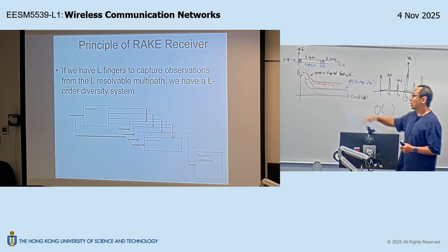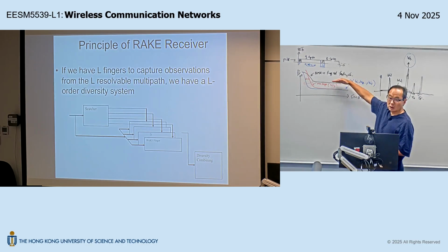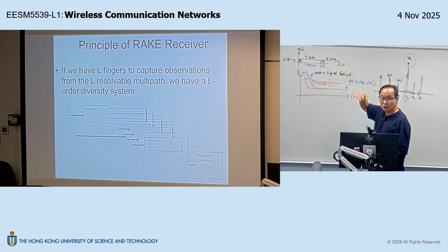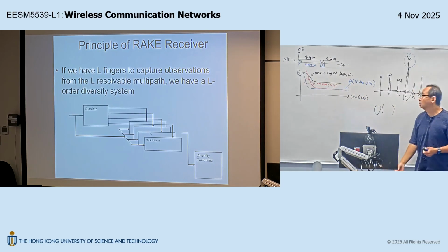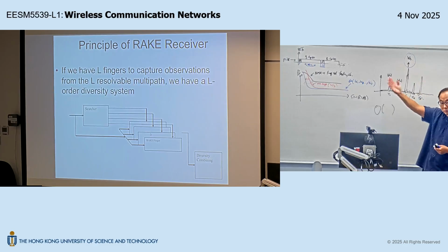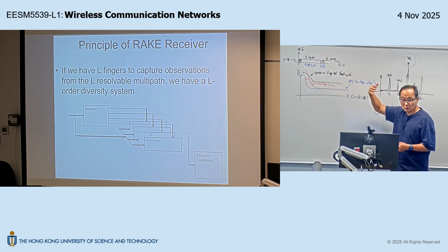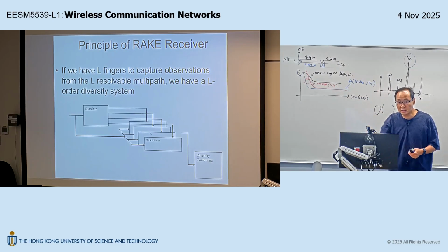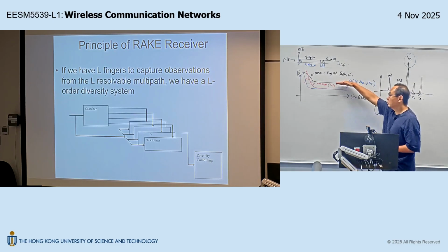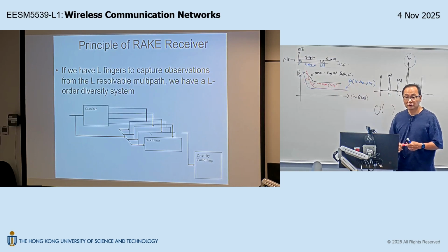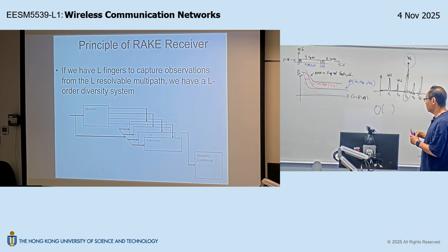Is that okay? Whereas in this case, the reduction of the error floor is determined by the spreading factor. It's the inherent interference suppression capability. If you are chopping a symbol into 64 pieces, you will get this 1/64 increase in the saturated SINR. So therefore, your error floor will be reduced. Is that okay? So what I have illustrated is, even with a single despreading finger,